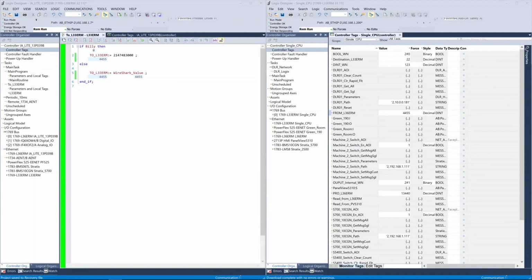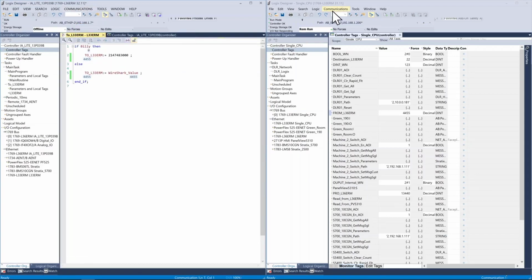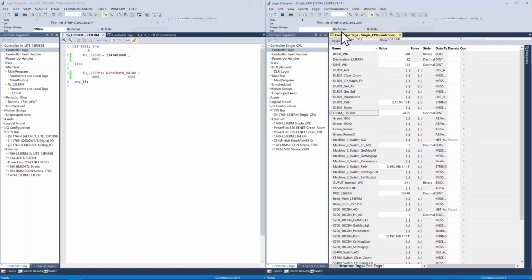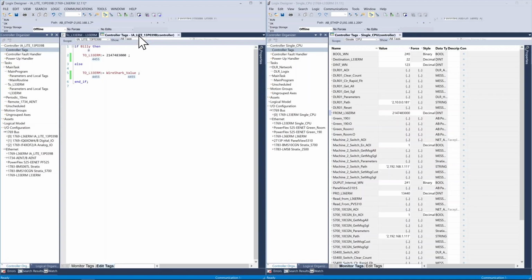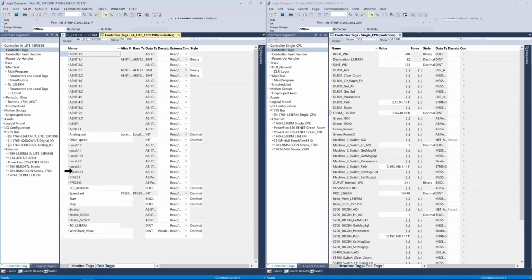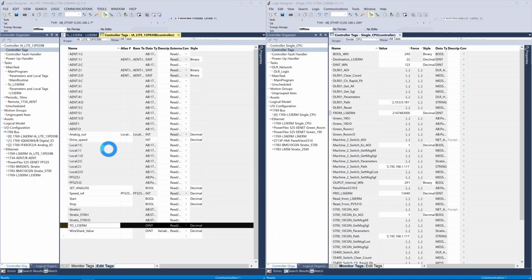In Studio 5000, in my PLC connected in port 2, I'm running a script. Structured text, very simple. This PLC is the L36ERM. In port 4, I have the L33ERM. The script basically follows a simple condition. If it's true or false, I will be changing a number. If it's true, it's going to be a large number. If it's false, it's going to be a very short number.